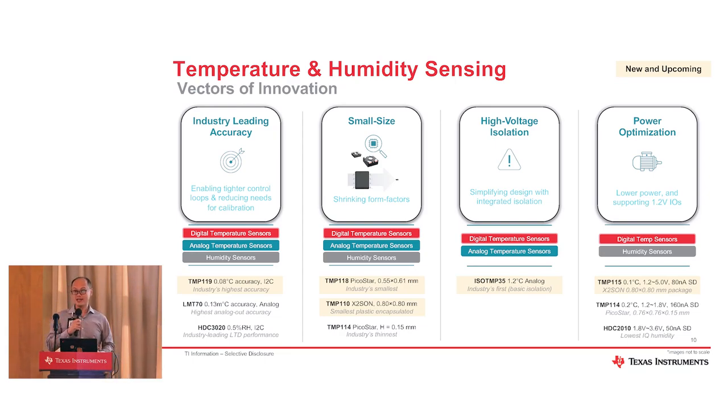We are also making it small size, for various reasons. First thing is that to have accurate sensing of the temperature across your product, you need to put many temperature sensors across your whole product. So if it's big, then your whole product becomes bigger, right? So we have to make it small for you. And of course, the other reason is that the smaller it is, the cheaper it is. Less metal, less lead frame is cheaper. So we have PicoStar package, we have our X2SON package for your small size options.